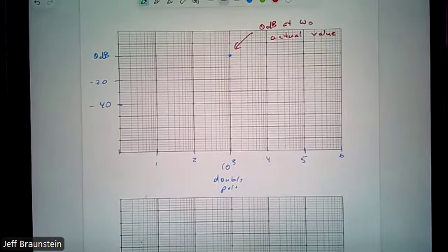But with that in mind, if I'm drawing the critically damped case relative to the straight line approximation, double pole, what's my correction? Minus 6 for a double pole, right? So if this is the actual value, then my straight line approximation has to be up here at plus 6.